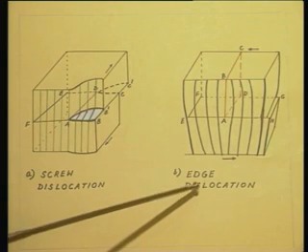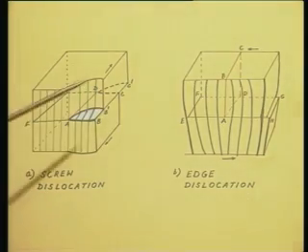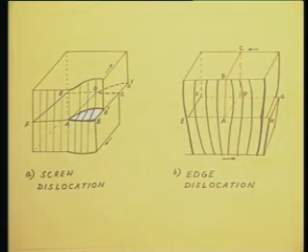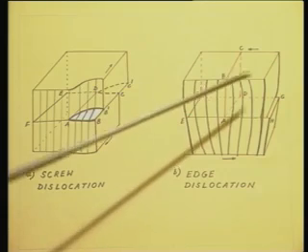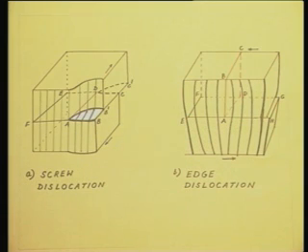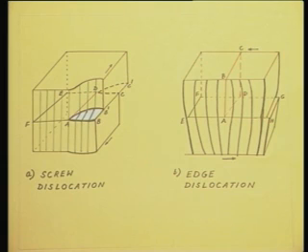The other type of dislocation is called an edge dislocation. It takes place along one line or one edge. Here also you can see this was originally an ideal crystal. Then we subjected it to a shear stress like this in this direction and in this direction. Along this face, we have subjected it to a shear stress like this and like this. So, what is going to happen? What is going to happen is this red line. This red line signifies one extra half plane of atoms.